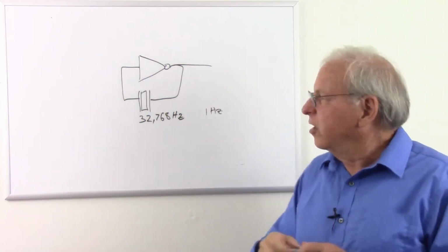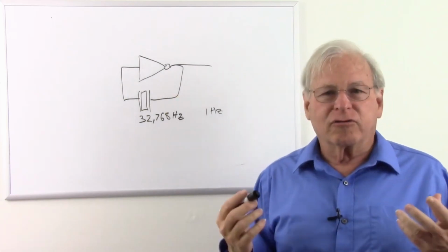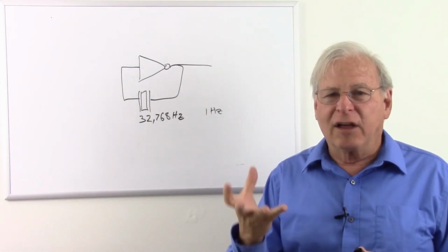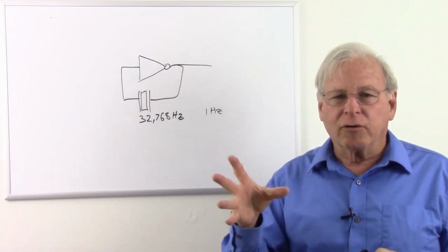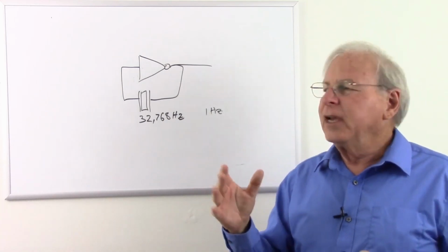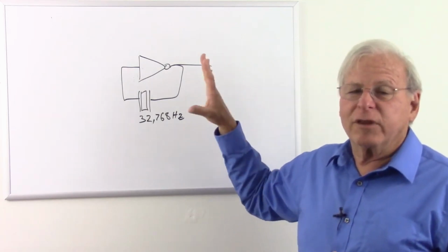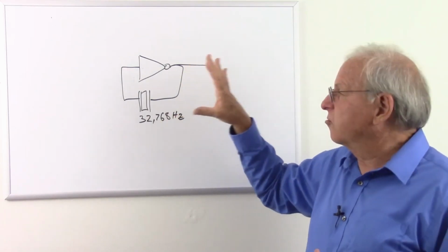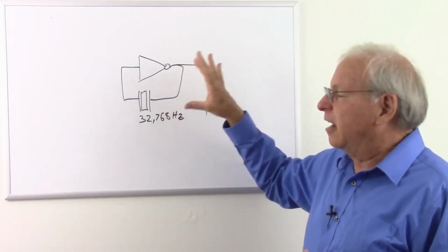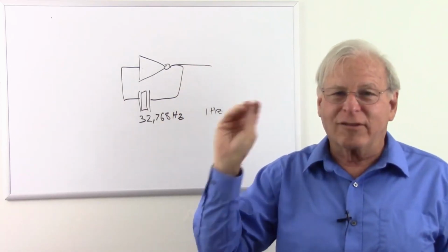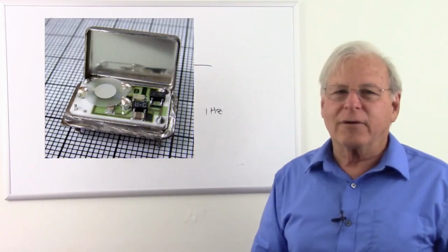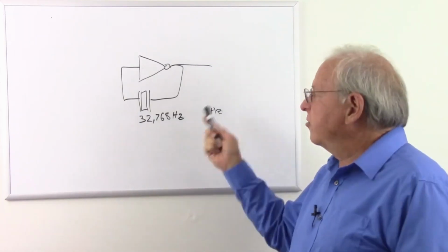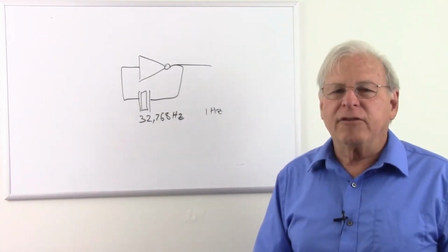Computers use the same kind of circuit just to run the computer, because there has to be an oscillator that makes the computer, every time it oscillates, go through one step of whatever it's doing. So digital circuits, especially those with controllers, microprocessors, or whatever are in there, have to have oscillators that make it do its stuff on each pulse. And those will be crystal oscillators because they're cheap and quick to make. So that's two places we see crystals using the piezoelectric effect.